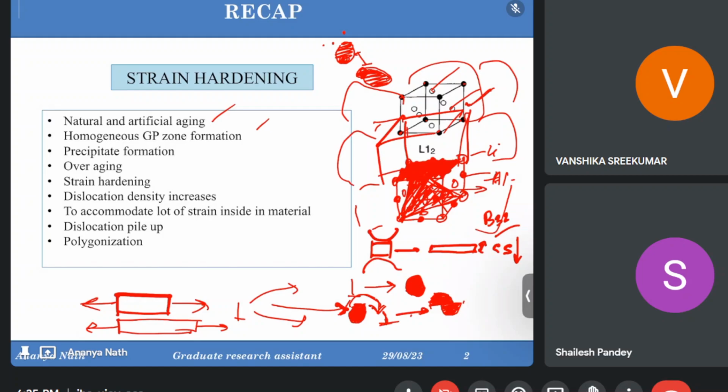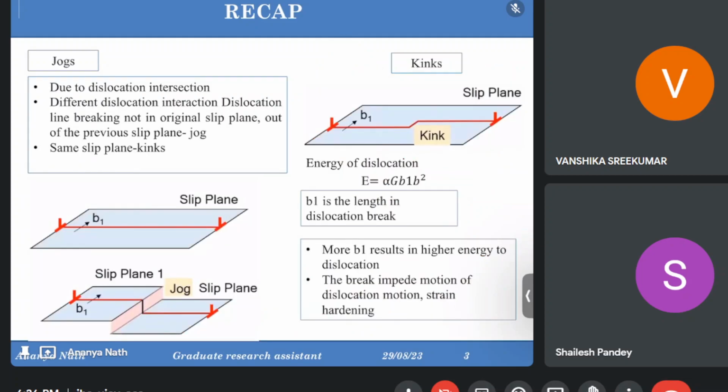We have increased the dislocation density in such a way that they will find it difficult to move because of themselves only. This type of interaction or barrier is called the Lomer-Cottrell barrier. It's very important if you are dealing with metallurgical work. Now, there are two types of dislocations, so the next slide is on the types of interaction and how they find it difficult to move.